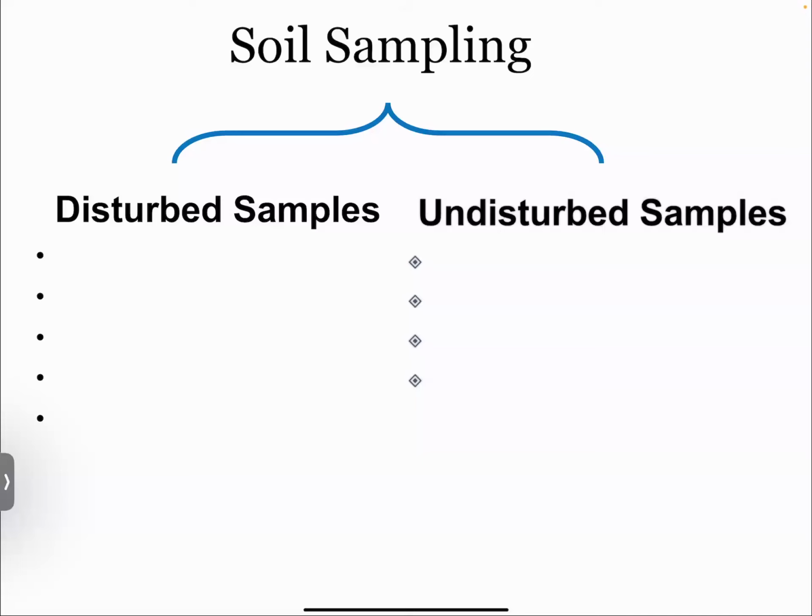All right, now we're getting to the soil sampling. So once we get to the depth that we need, there's different ways of getting the soil samples back up to the surface. In general, there's always going to be a combination of both of these, where you have drilling and then sampling occurring. So you would drill to the depth, and then you would replace that with a sampling technique, and then you'd retrieve the sample and then drill and then sample, drill and sample. So that's why the mobilization costs and the cost of this is pretty expensive.